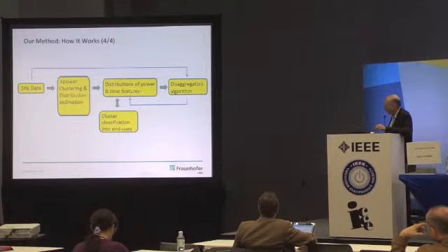If you're talking about a block scheme, this is how it works. We collect 1 Hertz resolution real power data collected for about 2 weeks. And then we proceed with a simple clustering algorithm. From it we get initial distributions of power and time. Then we use for the first time the disaggregation algorithm, get new distributions updated, and then we proceed once again with that. After that we will have updated distributions of power and time for each cluster. We can classify who is who. And after that, essentially, we can use this algorithm in near real time.